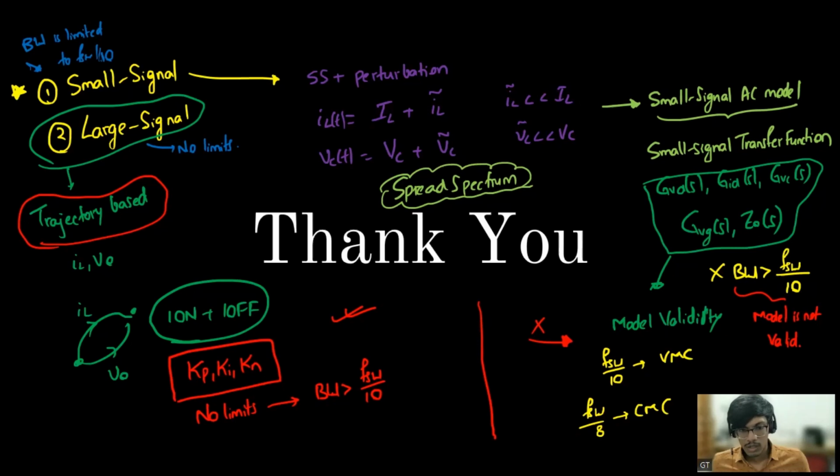Sir, in the small signal model, basically we are saying when we are using the small signal model, we are considering the circuit, the Buck converter, is already in the steady state. Yes, and we are considering perturbation. Yes, sir. But how to take that circuit from one steady state to another steady state?